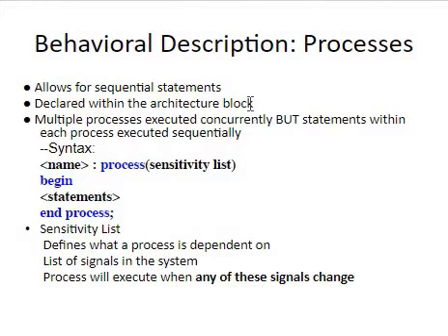So by default, VHDL architecture execution is concurrent, and if we want to design any sequential circuit using VHDL, for that we have to write a process. That's it. This is the crisp definition. Why do we need a process? VHDL programming is concurrent by default. If we want to design a sequential circuit inside a VHDL program, we have to use a process. No other option is out there.